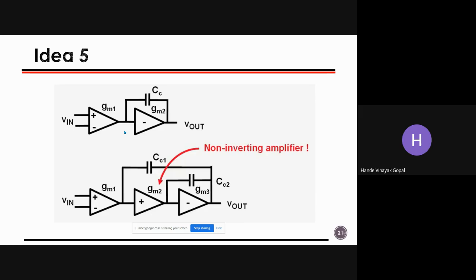So what designers generally do is that going to 2 stages is very, very common. They can go to 3 stages, which is not very common, and 4 stages only when it is really needed. Generally 4-stage amplifier is avoided because it creates a lot of stability issues if we don't stabilize it with proper measures.